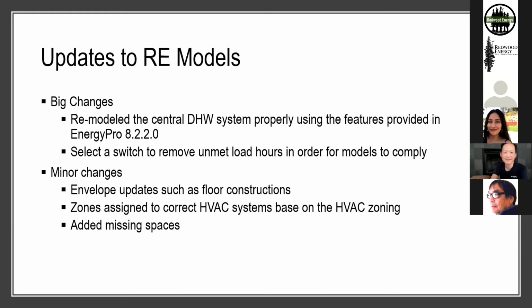But in this case, there is a switch in EnergyPro that will allow you to get rid of that non-complying margin, but it will still show up in the report, the zones that have unmet hours and need to be fixed.